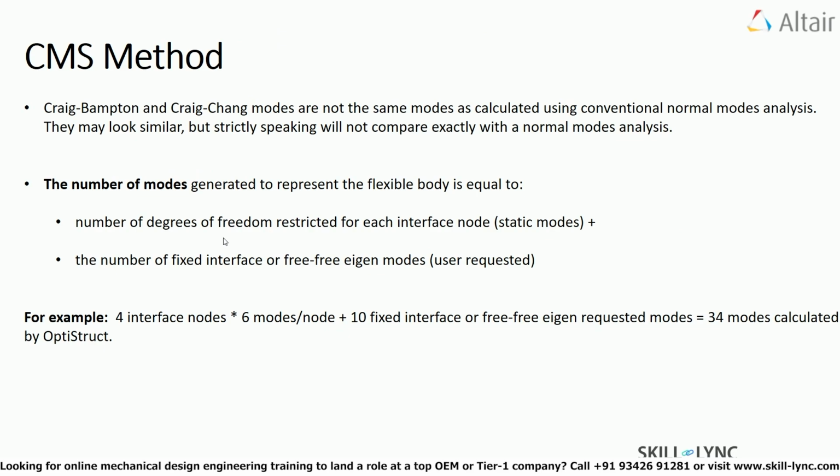I believe all those having a background in FEA understand the meaning of normal modes analysis. For those of you who don't know what it means, here's the explanation. A normal mode is a motion where all parts of the system are moving sinusoidally with the same frequency and in phase. All observed configurations of a system may be generated from its normal modes. Each normal mode has a characteristic frequency, that is, its eigenvalue.